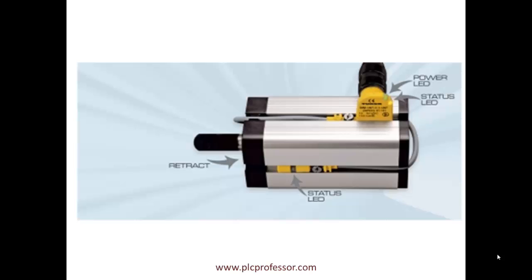There's a piston inside of this cylinder that can travel back and forth, and the cylinder has a port at each end. In the picture you can't see the ports, but they're there. Take a closer look at this photo. There are two sensors attached to the cylinder, one at each end of travel. They sense the position of the piston inside the cylinder. Each of the sensors has a status LED. If this status LED is illuminated, the sensor has sensed that the piston is at that end of the cylinder, or you could say in that position.